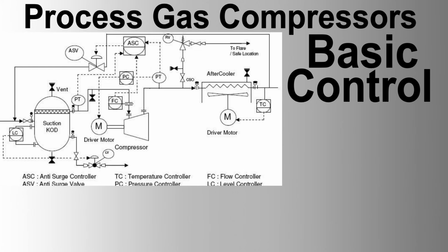Detailed loop configuration schematic. Suction pressure control: multiple compressors' suction lines, PTs, central PID controller, VFDs, control valves, compressor inlets. Discharge pressure control: compressors' discharge lines, PTs, central PID controller, VFDs, control valves, downstream process. Anti-surge control: compressors, suction and discharge lines, PTs and FTs, central anti-surge controller, recycle valves, VFD adjustments, compressor speed control.